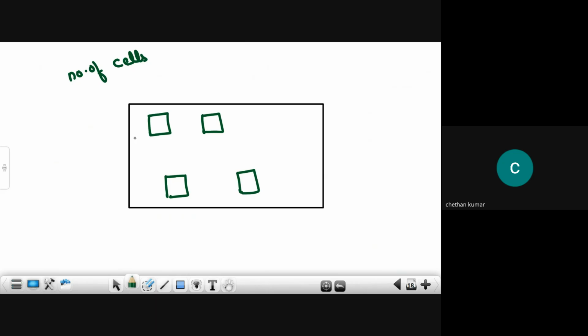We have one constraint on the size of the chip. That means the size of the chip must be within these limits. It should not cross that limit. So without compromising the size of the chip, in order to get less power consumption and the best performance, how the cells have to be placed is going to be decided by the placement team.